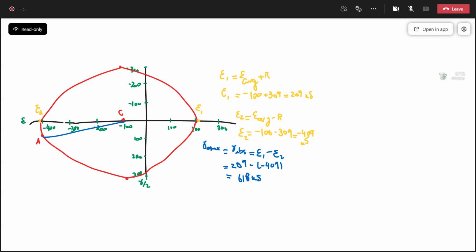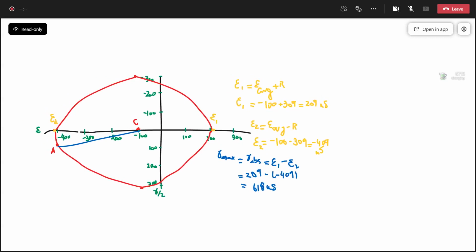सर ये हर केस में सेम ही होगी एब्सोल्यूट और इन प्लेन shear स्ट्रेन या चेंज भी हो सकती है? किस केस में? जब दोनों के ऑपोजिट साइंस है। When you will have one positive, one negative, तो ये सेम ही होगी, it will not change. You will only have one possibility when you have one principal strain positive, other principal strain negative. Positive principal strain will be epsilon 1 and negative principal strain will be epsilon 2. ठीक है जी? If this is clear or if you have any query, you can ask me.